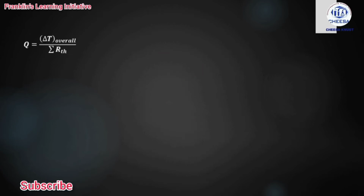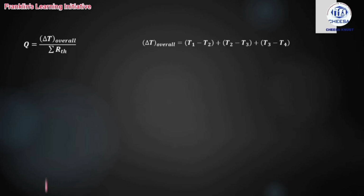The rate equation for the heat transfer through the composite wall is going to be the overall temperature difference divided by the overall resistance. We can calculate the overall temperature difference by the initial temperature difference, that is T1 minus T2 plus T2 minus T3 plus T3 minus T4. That gives us the overall temperature difference.